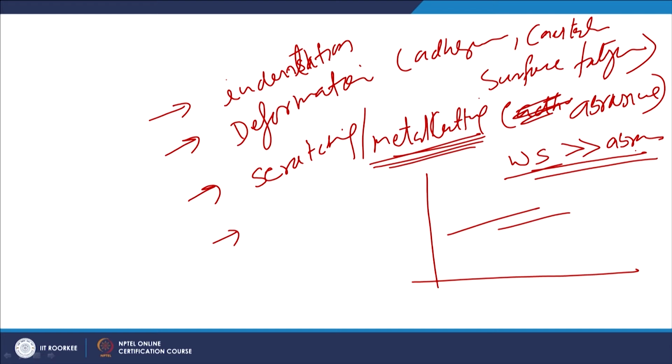So, in the choice of workpiece material or the kind of surface to be generated, if it has hardness close to that of the abrasive, then certainly it will reduce the wear, but it can make the material brittle also. Erosive wear is also affected because of this. Erosion is affected, especially when particles are impinging on the surface at a low angle, material removal takes place by abrasion, which is significantly influenced by the hardness value.